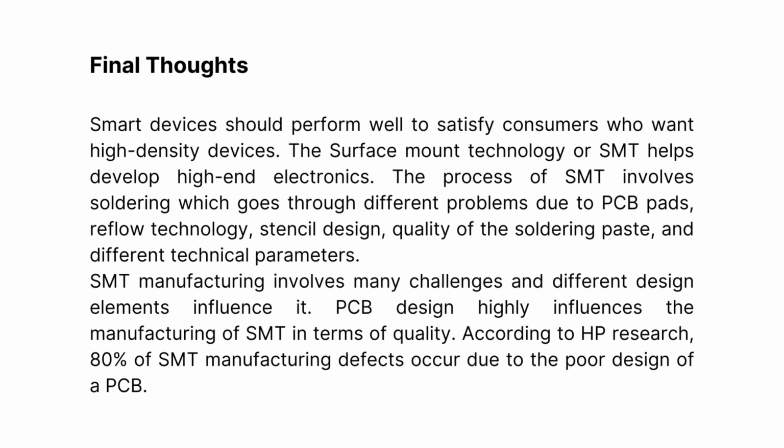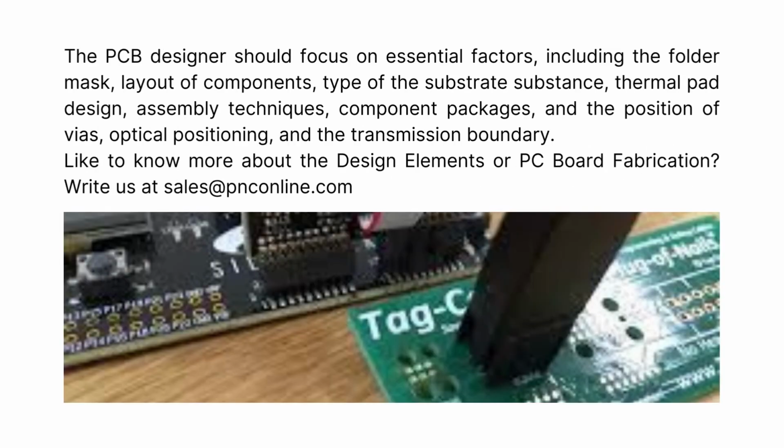PCB design highly influences the manufacturing of SMT in terms of quality. According to HP research, 80% of SMT manufacturing defects occur due to the poor design of a PCB. The PCB designer should focus on essential factors, including the solder mask, layout of components, type of the substrate substance, thermal pad design, assembly techniques, component packages, and the position of vias, optical positioning, and the transmission boundary.